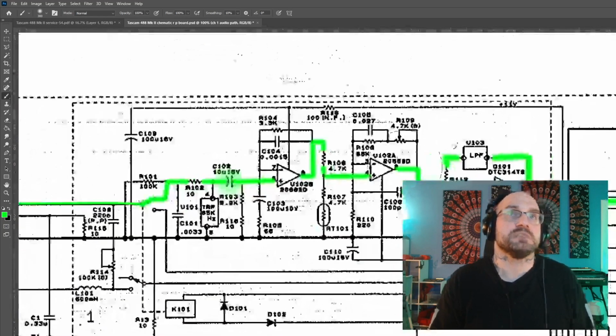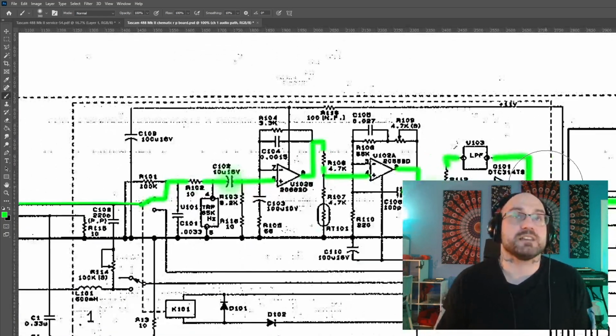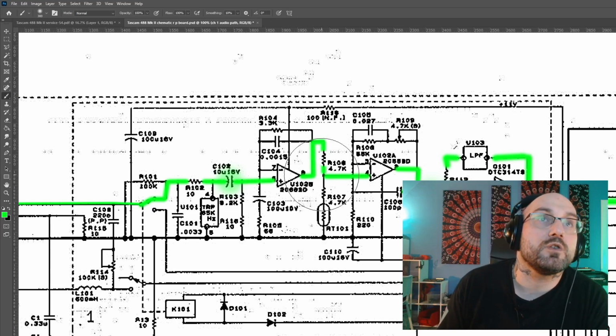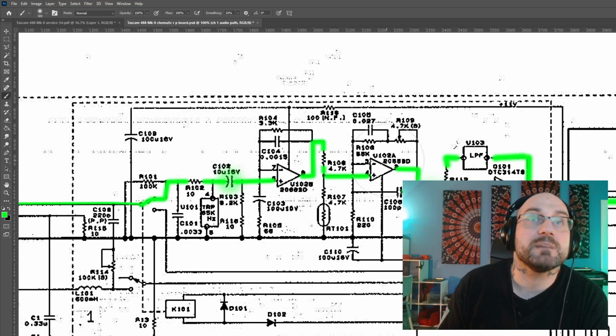of the system. But let's say this one's fine and this one isn't, then I could pick a point maybe halfway along there. So maybe I test on the output of this operational amplifier, and if the signal's okay there, then I know it must be one of these points to the right where there's a fault. But if it isn't okay there, then I know it must be that capacitor or the relay that's at fault. So you can kind of cut things in half when you're troubleshooting.